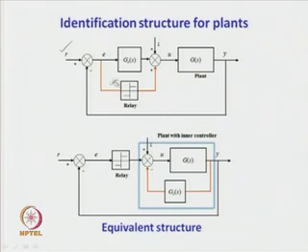So, although the relay is connected in parallel with the controller, the relay sees basically a process connected with an inner controller GCS, and GCS helps in relocating the poles of the open loop unstable original process GS and enables us to get symmetrical limit cycle output. So, this is the beauty of the scheme that is introduced now.